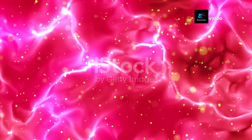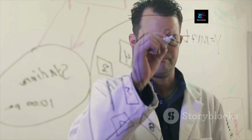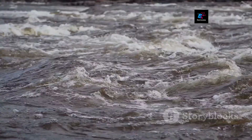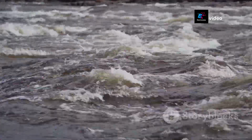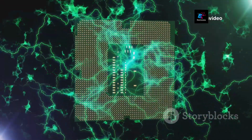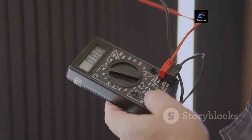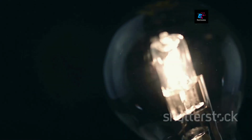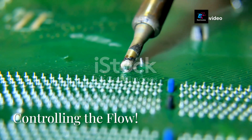We've got our electrons moving thanks to voltage, but how do we measure how many are flowing? That's where current comes in. Current is the flow of electrons through a circuit. Think of a river. The wider the river, the more water flows through it, right? Current is similar. A larger current means more electrons are flowing. Current is measured in amperes or amps. A small light bulb might only use a few milliamperes, while a large appliance like an oven might use several amps.